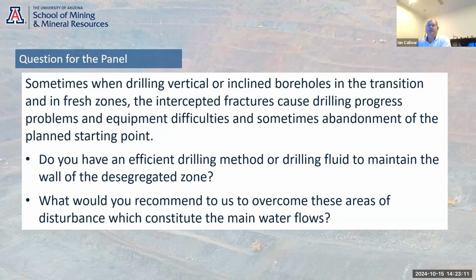So I was going to say, sometimes you're a bit limited by the gear you have. I have done projects in remote parts of the Philippines with an exploration rig, and impossible to get a hole through broken ground by conventional means. And we went to a casing advanced method, 8-inch casing. It was a big rig, but then used the old cable tool trick.